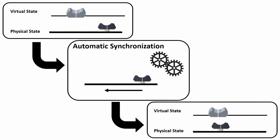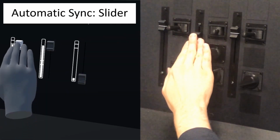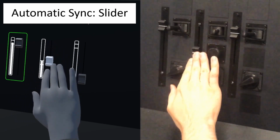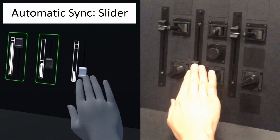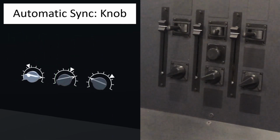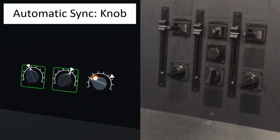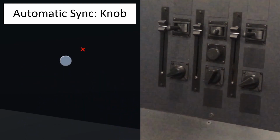In the automatic method, motorized controls are used to synchronize the physical control to the state of the selected virtual control. For sliders, we use readily available motorized sliders often found in studio mixing desks. For knobs, we initially tested motorized rotary potentiometers, however we found they moved too slowly. Instead, we used a motor with physical end stops to limit the rotation and an encoder to measure the position.